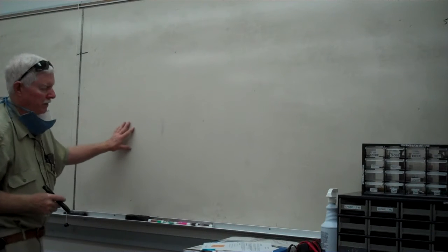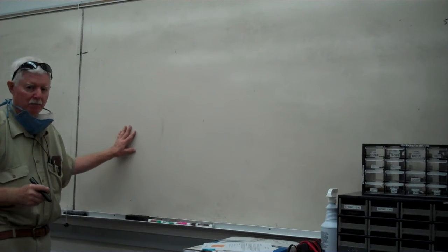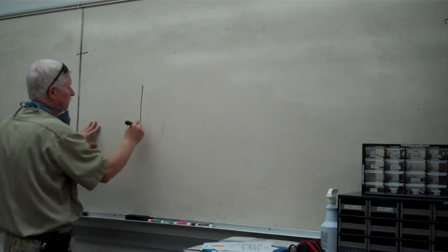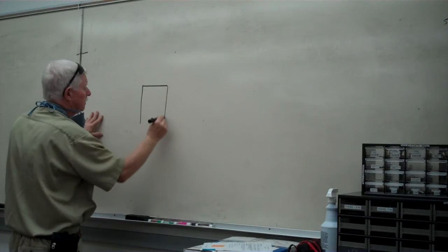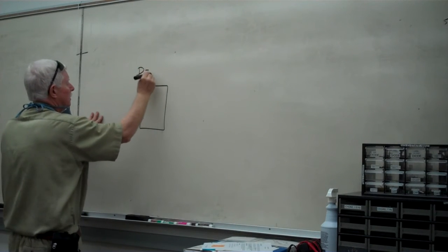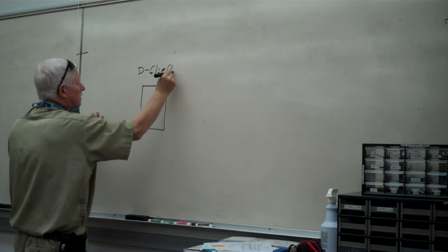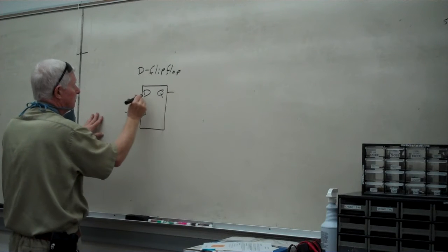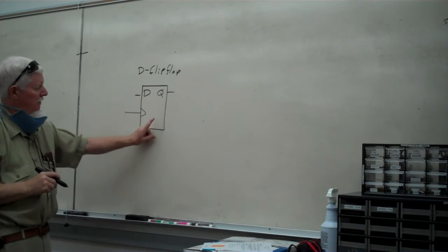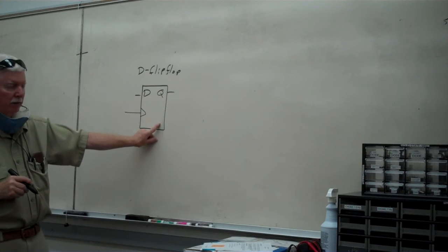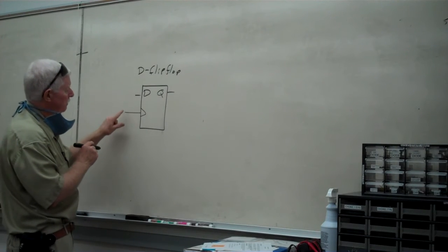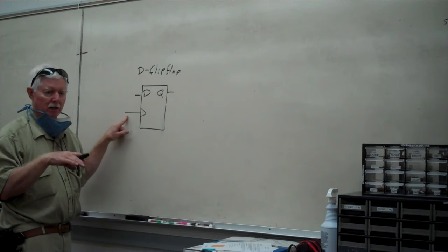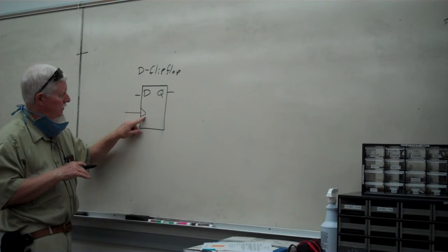The next type of circuit we're going to talk about is those that have some type of an edge triggering action to them. So let's take a look at these. Again, I'm going to use the D flip-flop. And in this example, I'm not going to use the not Q output, but most of these do have one. But this action is a little bit different from the enable. Enables are just requiring a logic high or logic low. They're level triggered devices. These are edge triggered.